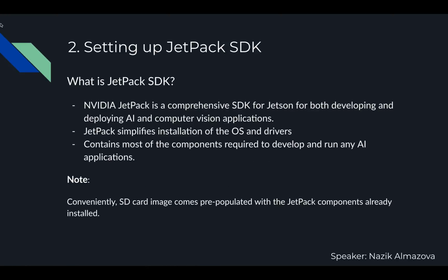The next step is to set up Jetpack SDK. So let's start with what is Jetpack SDK. NVIDIA Jetpack is a software development kit made specifically for Jetson boards. It contains most of the components and libraries required for development of deep learning and AI applications. Some of the components include OpenCV, CUDA, and TensorRT. For users' convenience, the SD card image that we burned earlier comes pre-populated with the Jetpack components, so we won't need to install anything.